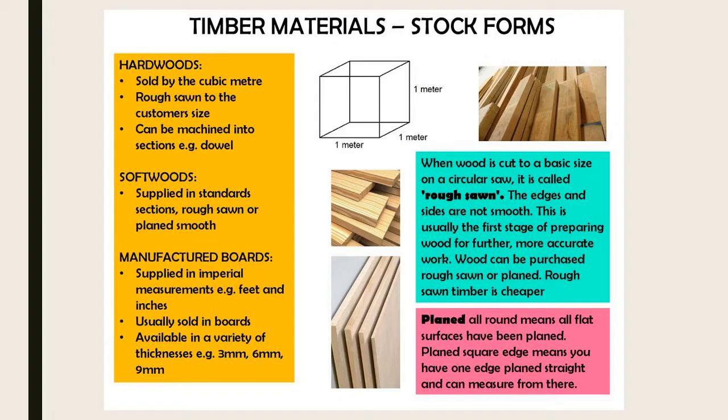So it's gone through a planer thicknesser, which essentially is a machine that has got almost like a razor blade esque blade on it, and you feed the material through on rollers, it'll go through and it'll literally just shave the very, very top layer off, and you can keep making it closer and closer together, and you can keep planing it down more and more, taking about a mil off at a time until you get it to the desired size, so you can change the thickness of it. But the main thing is, of course, that it then gets rid of any rough edges to it. Now that does cost more money because obviously it's more labour and you're using their equipment.